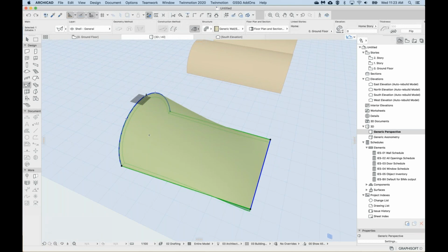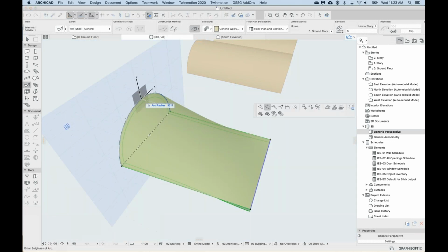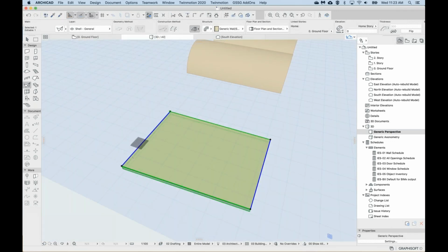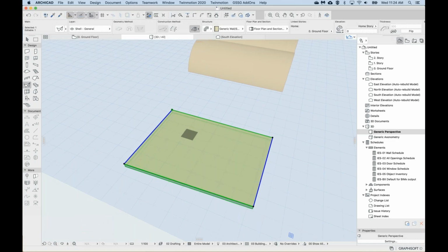So this curved edge, make sure you get the bold magenta, click on it, and then from the pet palette, choose the first option on the top row, so the insert new node, and this will flatten this curve. So basically, we just got two lines that are connected. So let me know if you've got two flat profiles. Okay, done. Got it. Great.